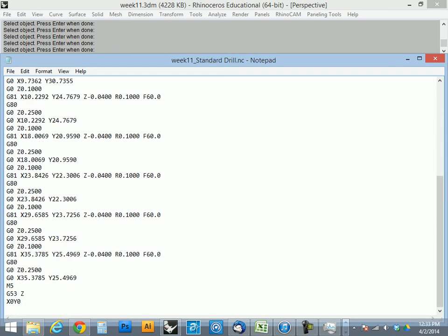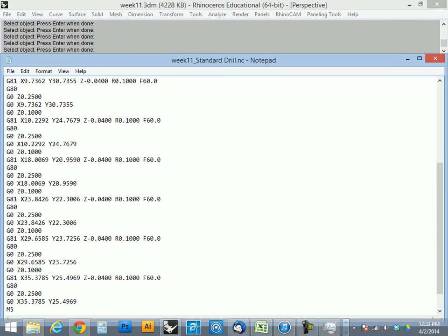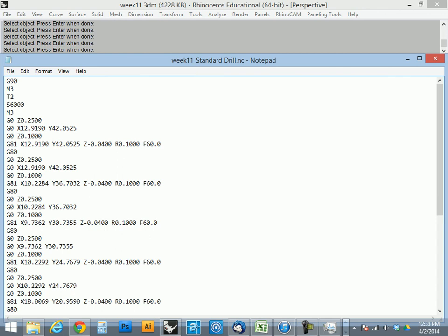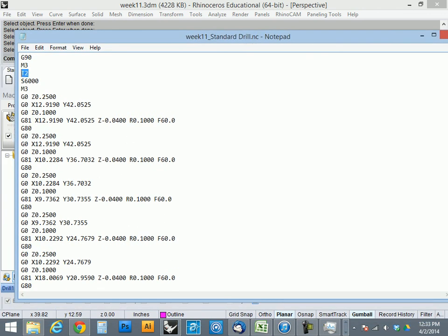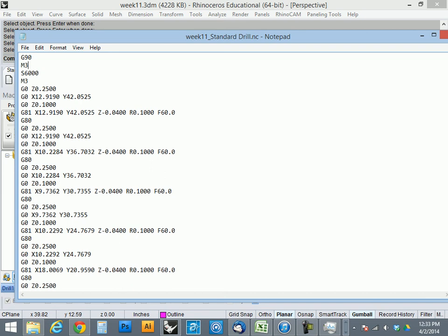This is the file. This is what's going to run to drill the holes. This is what G code is, yeah? The one thing we need to eliminate is T. T is the tool. So there's a tool changer on this thing where it can go and grab a tool. We're going to do that manually, and we're not going to change. So we delete the T and we resave it.